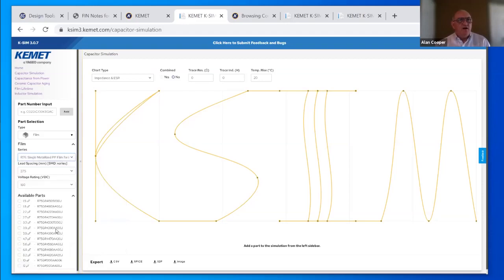The reason I looked at an R75 is because it's one of those components that KEMET has specifically designed for snubbers, for resonant capacitors, and for DC links. So that's where I would tend to start with looking at information or analysis to find a solution for this particular problem. There are others in the series. If I need to tweak it up for higher temperature, I'd take the R75H. Then if I need to do higher DVDT, I'd look at R76. But let's just look at this one for the moment.